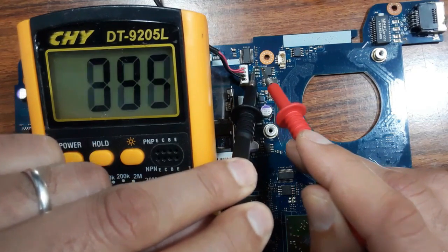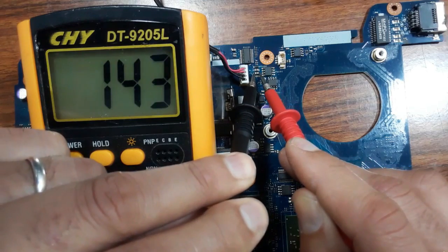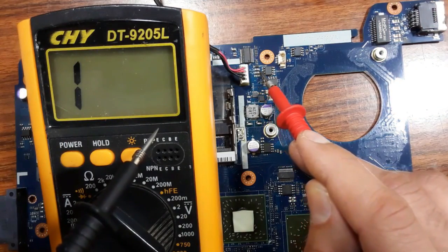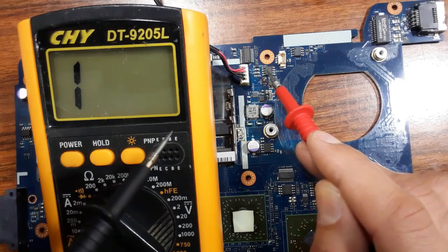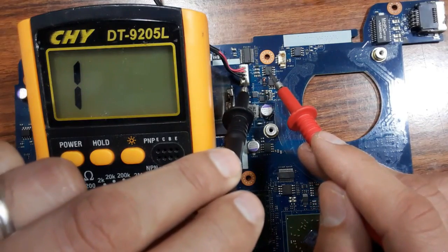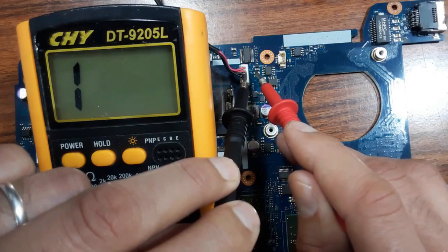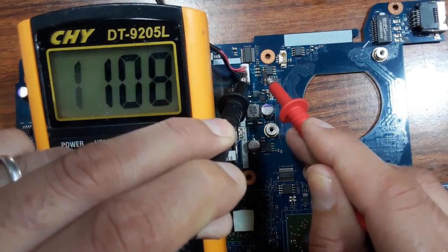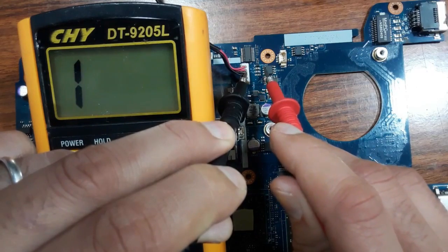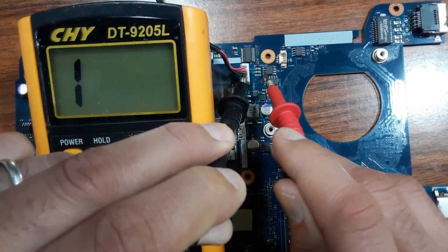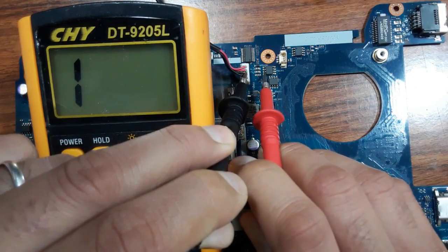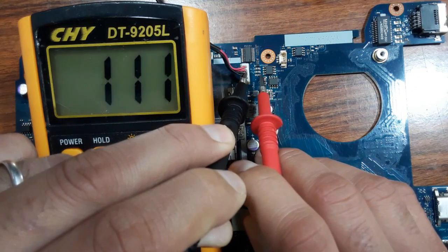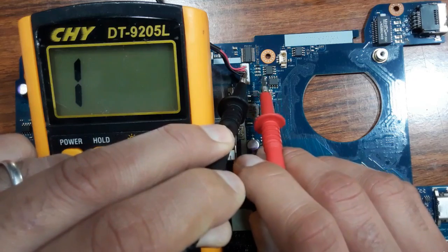This is a good coil. The second coil is good. Then 20 volt will pass through these coils and then goes to this MOSFET. So let's check this MOSFET. It will pass through these coils, as you can see, and then goes to the drain of this MOSFET. This is the drain. These 4 pins are connected together, as you can see, because this is the drain.